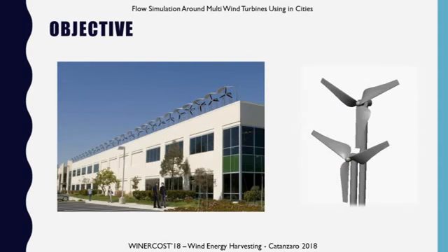And our idea is, as I mentioned, to place micro-wind turbines on the top of the building, similar to this picture, but in our case it would be in two rows, and the second row would be shifted by one radius in horizontal direction, thus taking advantage of the downwash coming from the first row to the second row. This configuration is based on a previous research which investigated the influence of two turbines on each other.